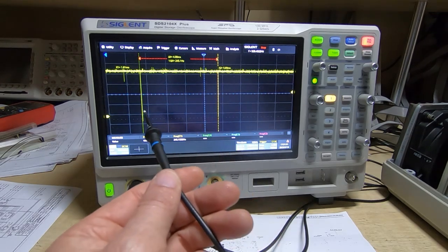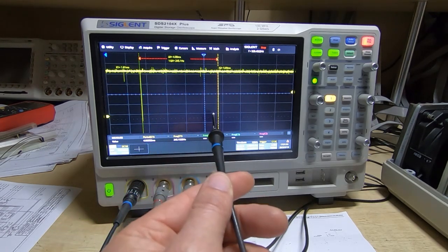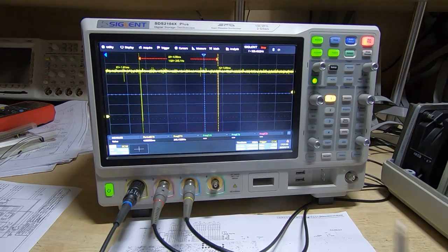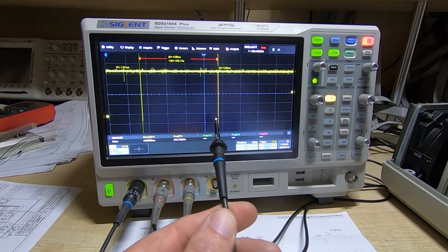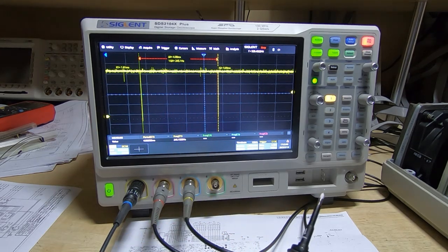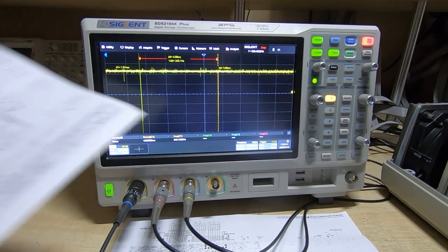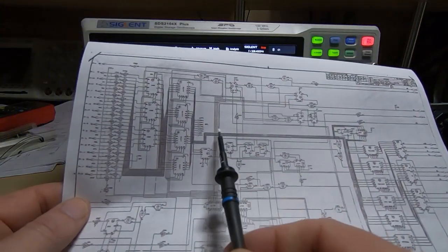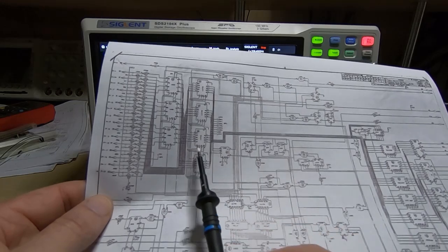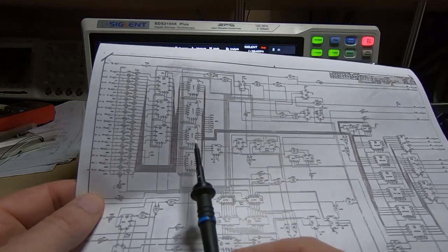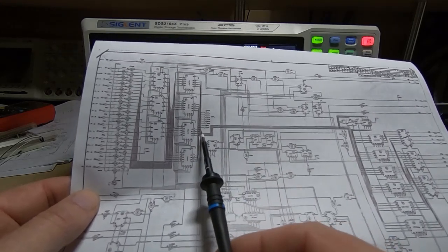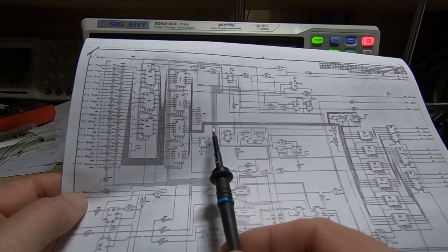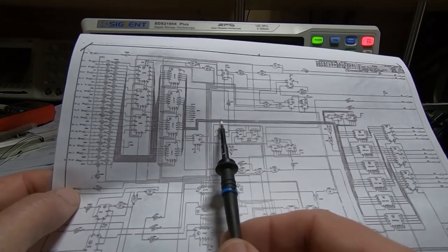And so we're getting a reload of the counters at exactly 1/4 of the interval rate. So it is starting to look very much like this is a problem with the counter, the address counter, being reloaded when it shouldn't be. And that can be done in response to the system receiving a control code through one of these devices, so it's either this one or this one, that aren't passing on the correct data value. That can also explain why we're seeing odd characters on the screen. It's just not passing on the correct character for certain rows.